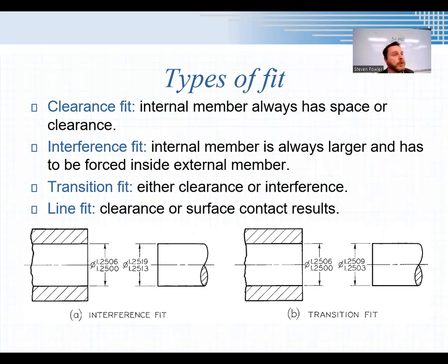What we do a lot of times with 3D printed parts, if you send me something, sometimes I'll think to ask, how much did you think about tolerances? What kind of fit did you design here? If it's early in the semester, it's your first prototype and it's something small, I don't mind if you send me a line fit. I don't mind printing them and handing you sandpaper when I hand them to you, because you're going to have to sand one to get it to fit inside the other, most likely. I say that, but I do have one really nice printer out there that I've seen make line fits and they fit perfectly, and it takes away my thunder of handing you sandpaper and saying, here, lesson learned, right?